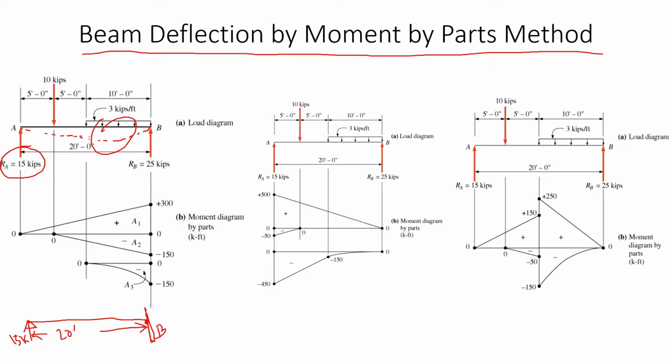We use the same cutting convention. If it's cut here, there is another moment applied here to balance that. So M at B, sorry, that's B. If we do this anti-clockwise, you see that 15k will do a clockwise moment, and this one is anti-clockwise. So the summation of all these moments, MB, is equal to 0.